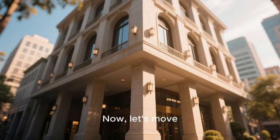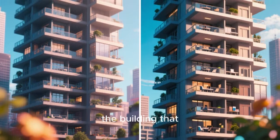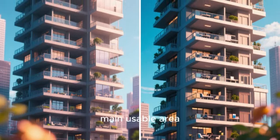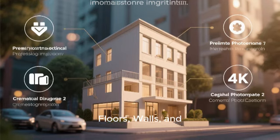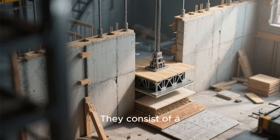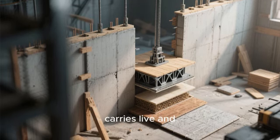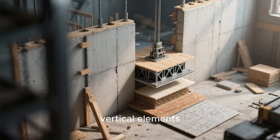Now, let's move above ground to the superstructure. This is the part of the building that sits on the substructure and constitutes the main usable area. The primary components are the floors, walls, and roof. Floors are the horizontal elements that divide the building into stories. They consist of a structural slab of concrete, steel deck, or wood that carries live and dead loads, and a finishing layer. Walls are the vertical elements.